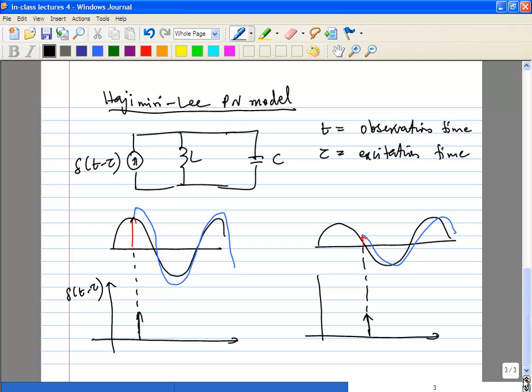Well, the thing is, the impedance of the tank at DC will be zero, because of the inductor. That is definitely true. Even if it won't create a voltage, if you inject a DC current, it will all be bypassed through the tank, right? That is perfectly valid. Actually, at the peak of the cycle the capacitor is fully charged, and when you inject current, it will go with the capacitor. Yes, that's right.